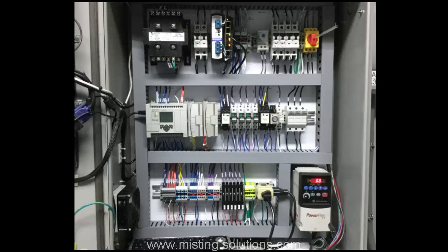signals out. And as you can see on these groups of terminal blocks that I just discussed, there is a color coding to them. Purple is for 24 volts AC, blue is for 24 volts DC, white is for the negative side of the DC and also for the other side of the 24 volt AC source. Green, as you can see, is ground like it usually is. Orange is signal control wires. These are the sensor control wires that go back into the Allen Bradley controllers right here and right down here. That's where those orange wires go.